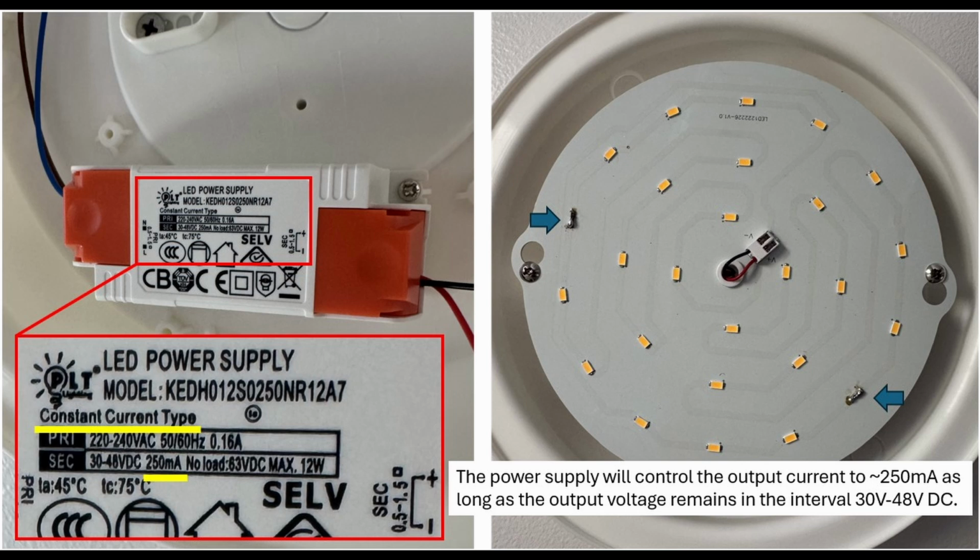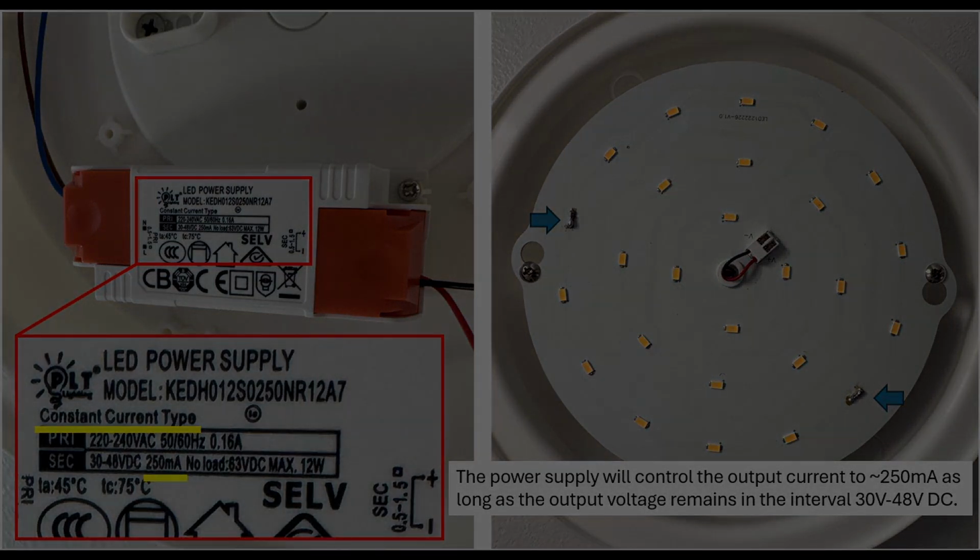Because it's a constant current device and the same current goes through all the LEDs, I just replaced these two LED positions with a solder bridge. It seemed to work quite well for 15 to 20 seconds, but then I lost half of the LED lamp, and something was wrong, so I turned it off and went into some more detailed troubleshooting.